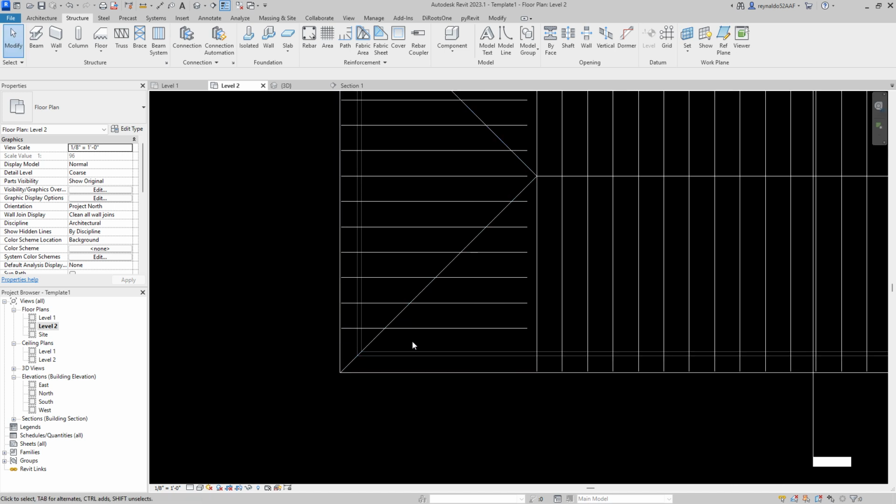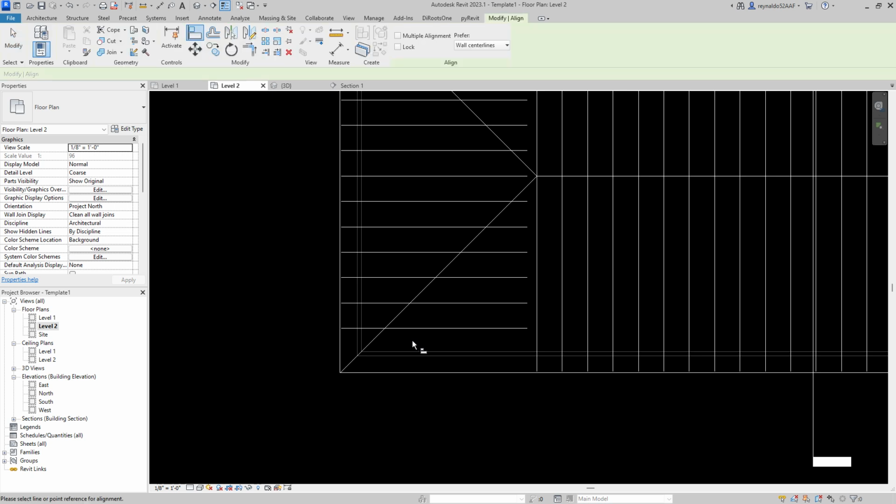If I do a line, click on the edge I want to cut, for it to cut, and then click on the item. Take that back. Sorry, I apologize. You want to do trim. You click on the edge you're cutting and the edge you want to keep, and you do the same thing here. You do TR for trim.